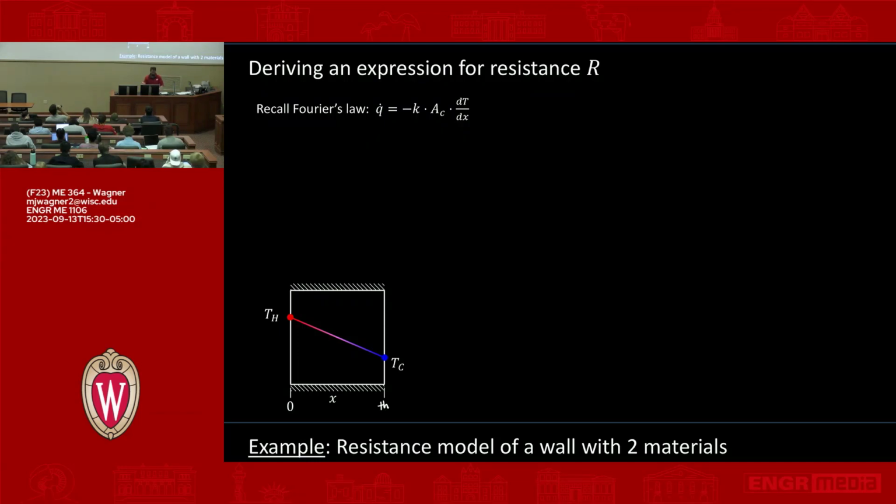By the way, hopefully at this point you are becoming more familiar with the procedure, so I'm going to go through it quickly. We have our heat transfer rate. If you do the control volume analysis, we end up with dQ dot/dx equal to 0, borrowing from where we ended our previous analysis. So let's take our rate equation and substitute that in: d/dx of minus k A_c dT/dx is equal to 0.